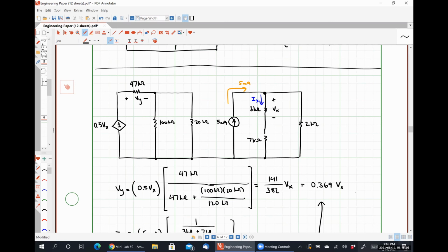That being said, what I'm going to talk about tomorrow, I've decided to move some things around. What I'm going to talk about tomorrow is an analysis technique called nodal analysis. Nodal analysis is effectively a method by which to solve circuits with multiple unknown voltages by using multiple applications of Kirchhoff's current law.